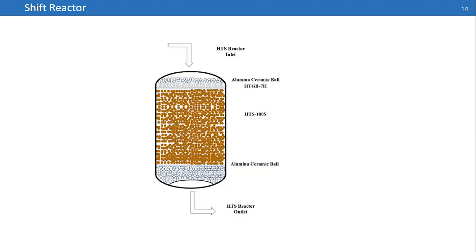In the case of the reforming reaction, it's difficult to reach equilibrium points. In industrial scales, you reach something like 1% of methane as slip methane outside of your reactor, and I think the equilibrium is lower than this value, which means we are a little bit far from the equilibrium point.